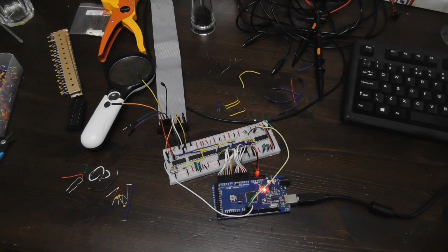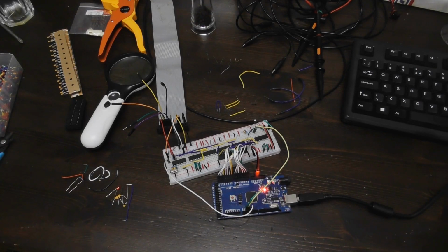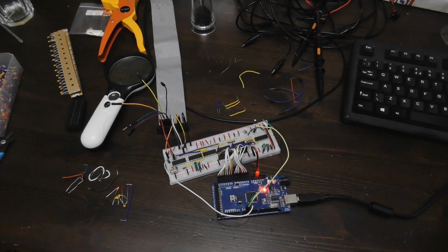Another option might be to plug the data byte of the shift register into a 6522, and then you can connect the clock signal here into one of the control inputs on the 6522, and for port A the 6522 can actually latch the incoming data when the control changes state in the correct direction. So that could be used as well for a sort of really lightweight way of latching this stuff, especially if it was being used in a 6502 computer. So that's probably the kind of thing I'll do next.